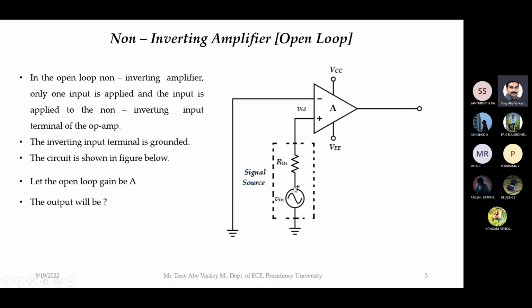Just V in. What is the voltage at the inverting terminal? 0. So what is the differential input voltage, VID?